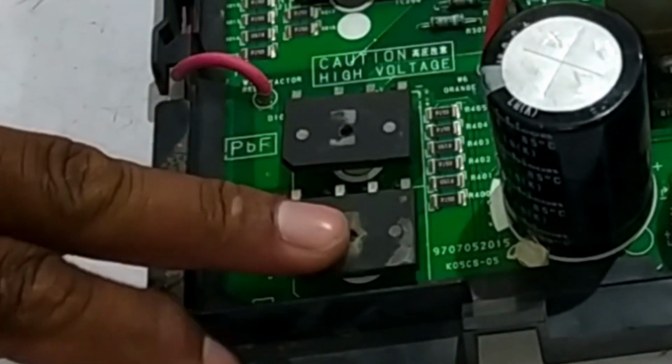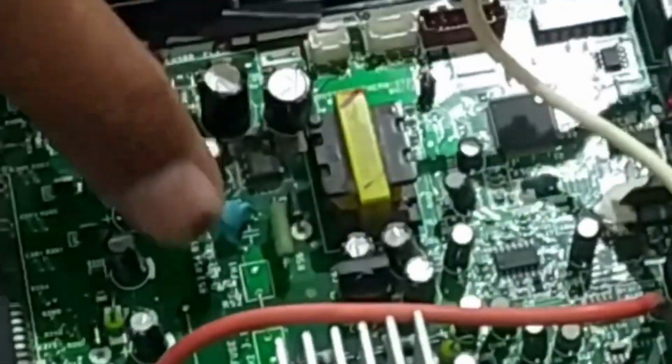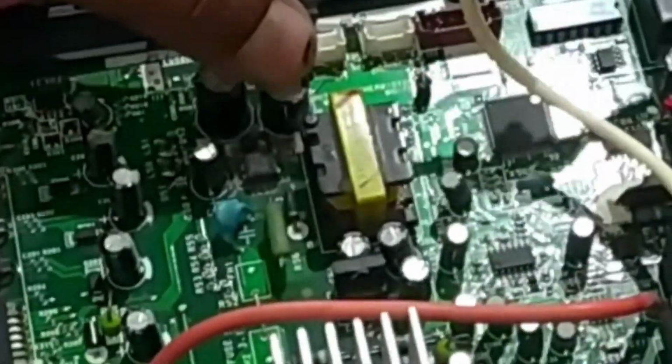If both rectifiers are working fine, the next step is to check the SMPS, switched mode power supply, and inspect the switching IC to ensure they are functioning properly. This process helps in identifying whether the power supply section is working correctly or if there is a fault in the switching circuit. Often, the SMPS develops a fault where it works intermittently, sometimes functioning properly and other times failing. In the unit I showed you earlier, it initially ran but then shut down, which was due to an issue with the SMPS. After replacing it, the unit is now working fine.